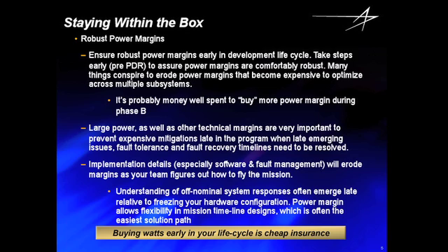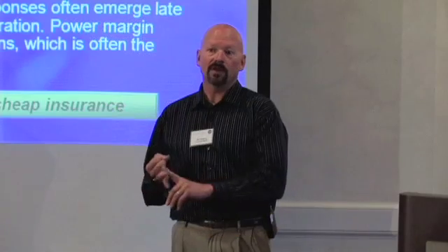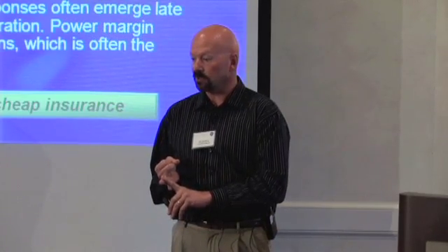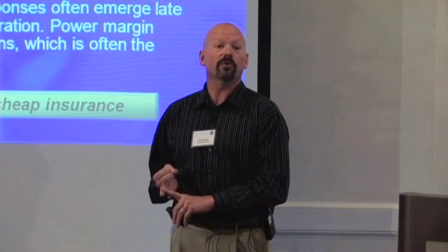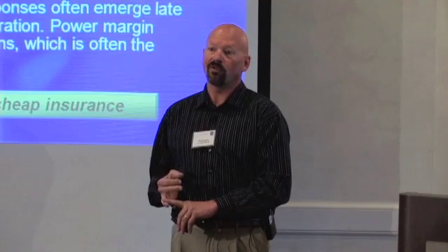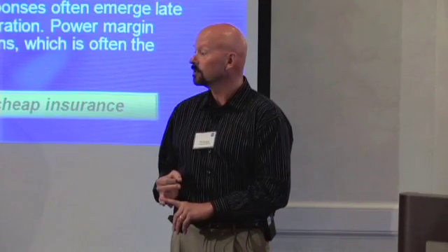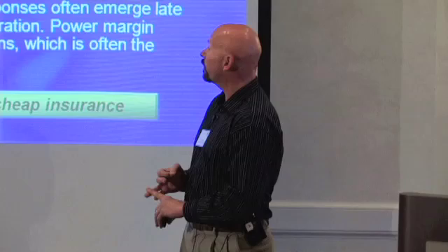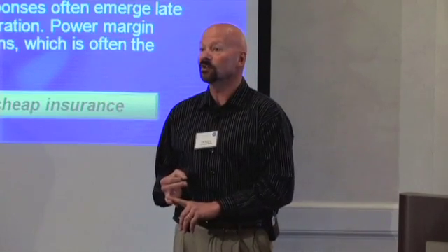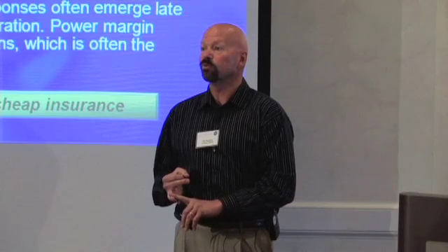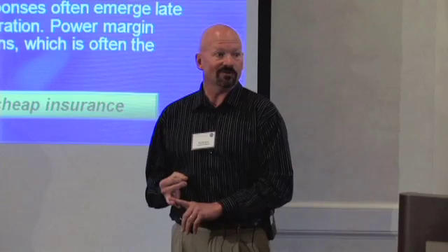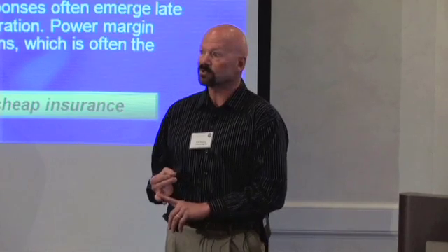You're going to find out that you needed more power for thermal, and that you had temperature gradients that you hadn't counted on. You're going to have to put more heater power into keeping your alignments because of thermal distortions. And you're going to find out, when the fault protection team starts rooting around in here because you're going to another planet, outside of Earth orbit, and you can't talk to this thing all the time, you're going to have 2 contacts a week or something like that.